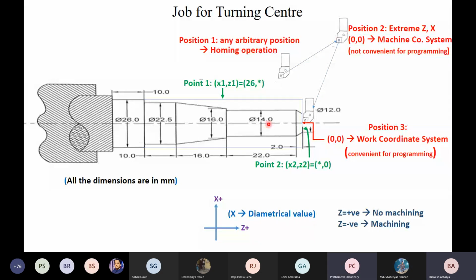Now sir, if the tool is at origin and we write x26, then it will move to the upper edge or the upper surface. Or we have to write x13 to move the tool to that upper point, point 1. For point 1 we should write 13. If we write 26, it will go ahead. Okay, just wait. When we discuss the entire program, it will be more clear.